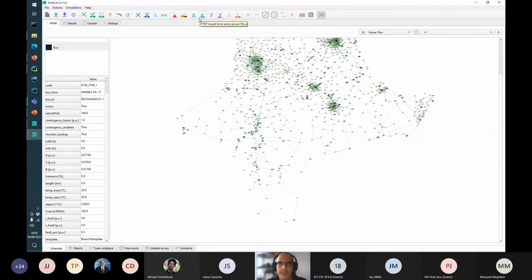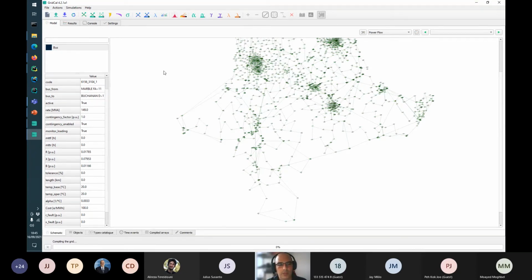I wasn't really interested in these linear things because they are not so accurate. Let's run the complete power flow and see. But still, they are super useful because they give you a hint of what's going on in terms of flows, at least. And of course, you can also run the contingency. And this one is the net transfer capacity between areas and a number of things.